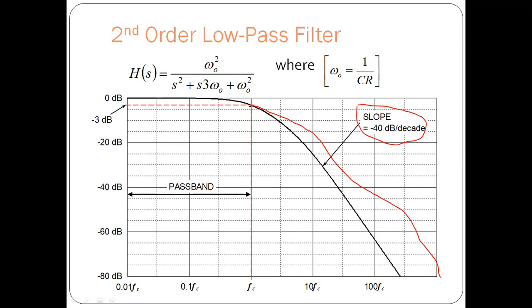then this attenuation will come towards this line. In such a way, we are bringing our practical filter response nearer to the ideal filter response by considering different numbers of RC circuits, that is, the number of low pass RC circuits which are connected in series.